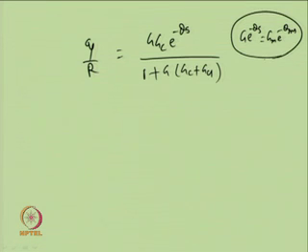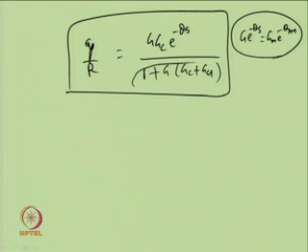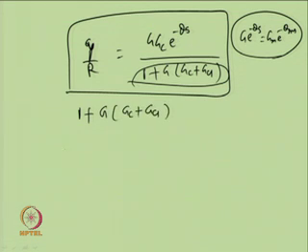Now, what is the benefit we are getting from this modified Smith predictor control scheme? If I carefully look at the denominator of the closed loop transfer function, it has got the controllers G c and G c 1 present in the denominator, which were not there in the earlier modified Smith predictor or the conventional Smith predictor and controllers.